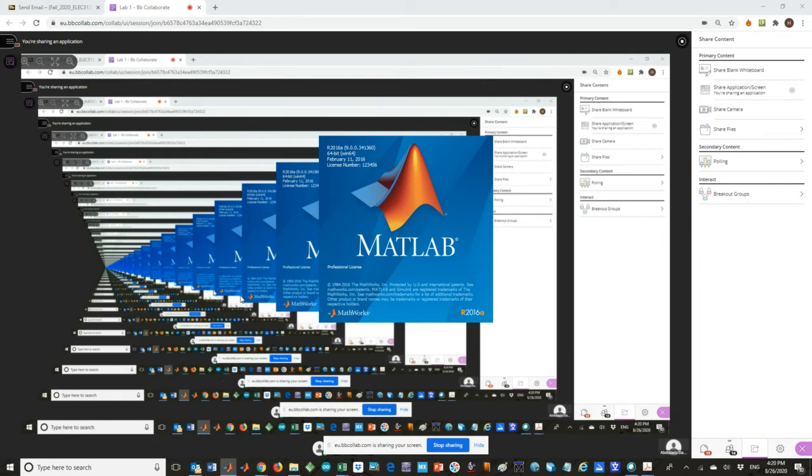Okay, so now I launched MATLAB. Yes, Mohammed? I launched MATLAB, so that's the first step to do if you need to work with Simulink. You have to open MATLAB first, and from MATLAB you can launch Simulink, another window separate from that one. But they are connected. If you open MATLAB and after that you open Simulink and you close MATLAB, you're going to close everything. So MATLAB should be open all the time behind the scenes.